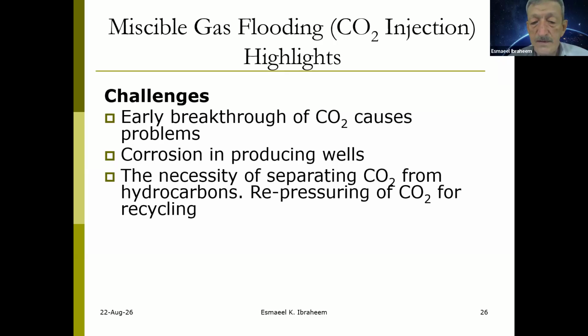Also, the necessity of separating CO2 from hydrocarbons and repressuring of CO2 for recycling. After production, the CO2 has to be separated from the mixture, and you have to pressurize the CO2 again to be liquid in order to be recycled and re-injected into the wells.